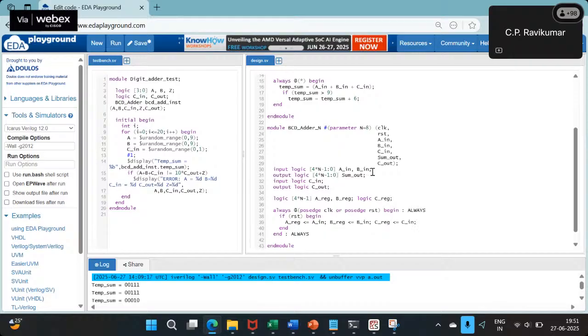And maybe some reg we can initialize to 0 or something like that. We need a sum reg also. We will initialize the sum to all zeros, right? And maybe we need a counter. We need to track how many times we need to do this, right? So the number of times is 8 only, right? So we need a counter which is initialized to maybe n, right?